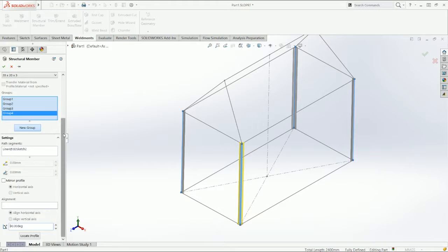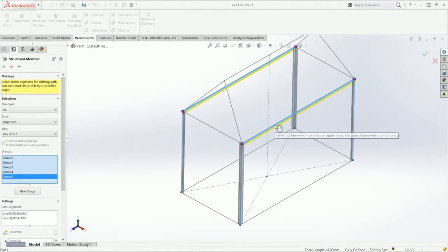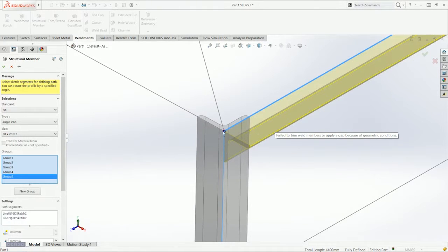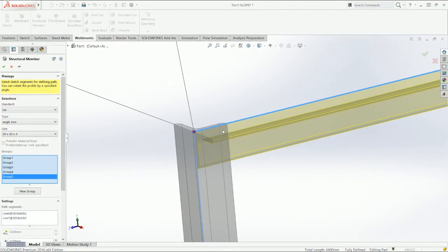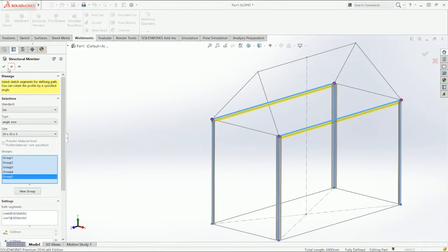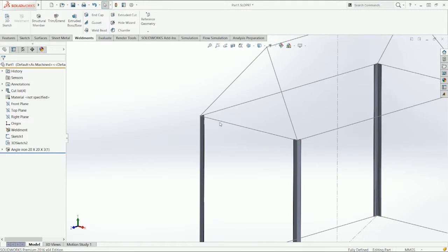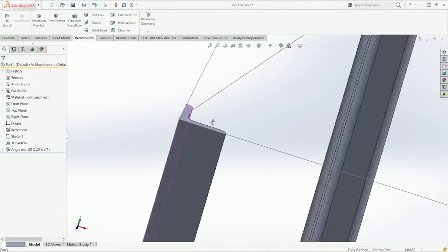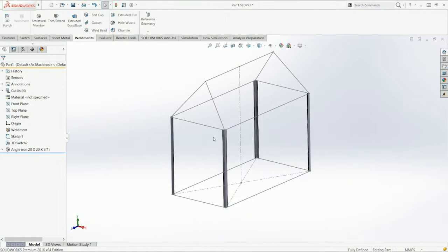So in the last episode, I showed you that you can do groups, which will allow you to change this right here. But in this case, I want to show you another feature, which is the trim extend feature. So I'm just going to right click in the group and delete it. So that's gonna let us do the profile here. Create the profiles and keep the same sketch.